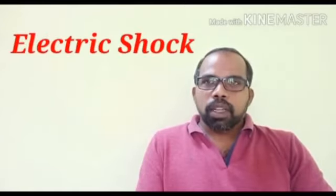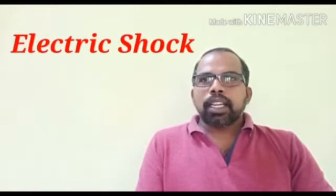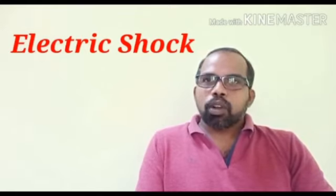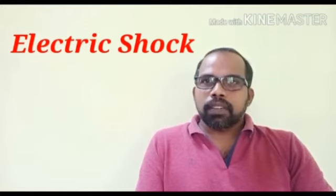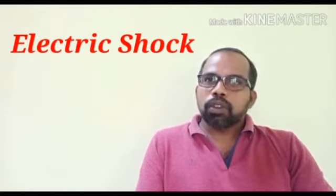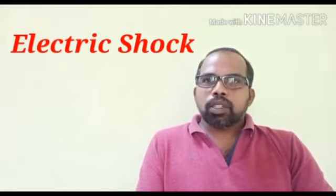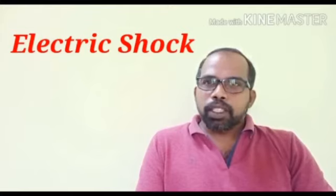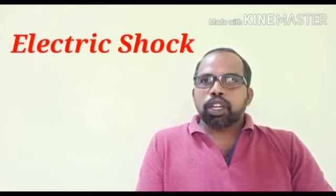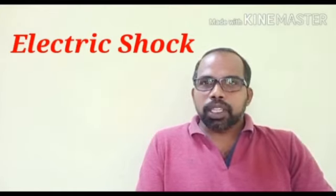Next, we are going to discuss electric shock. Of the accidents related to electricity that occur in India, about 10% take place in Kerala. Electric shock often leads to death itself. Hence, electricity is to be handled with utmost concern for safety. In addition to electric shock, blisters may also occur. If somebody gets an electric shock, the main switch should be switched off immediately. Then separate the electrocuted person using a dry wooden piece or a dry insulator material.